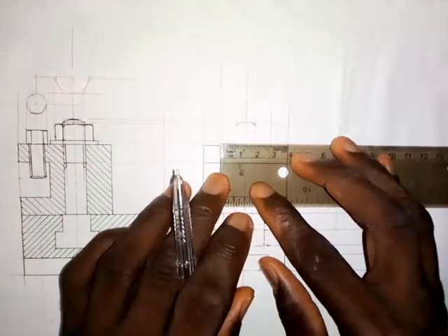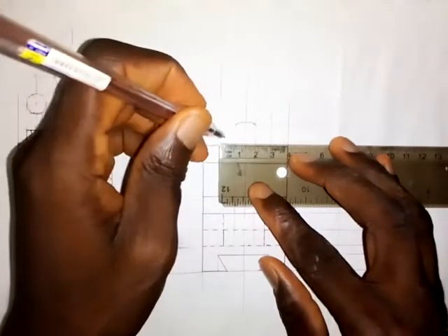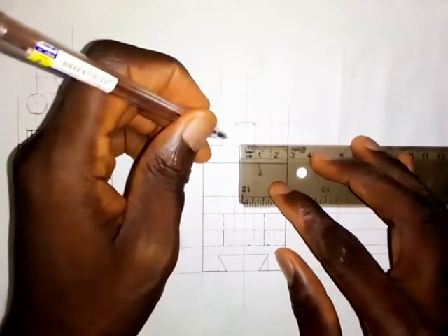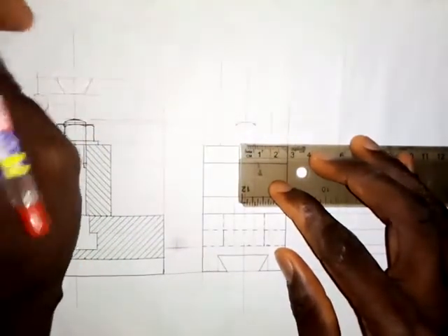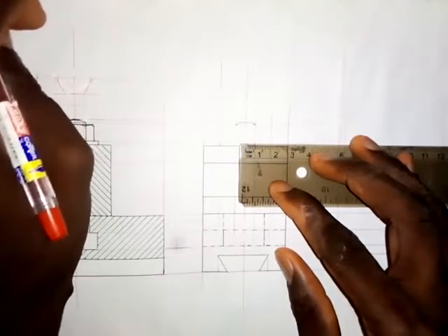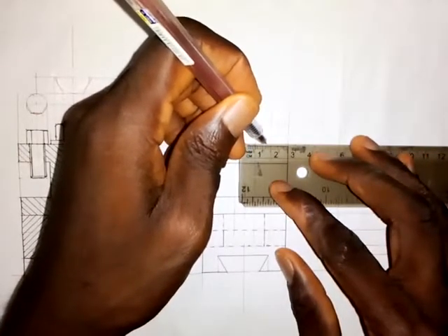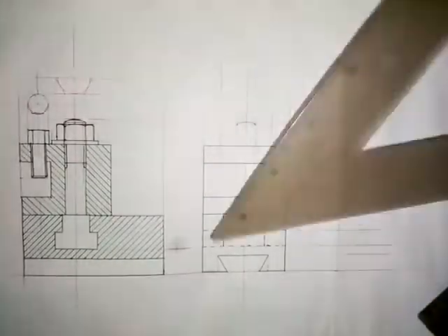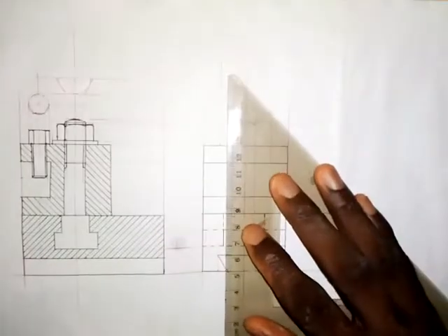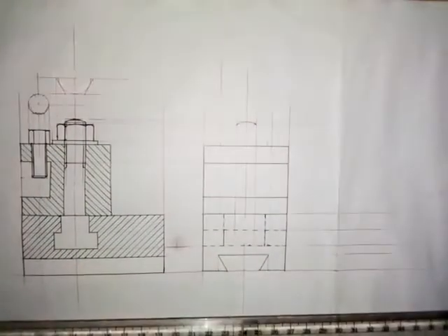I will take a measurement of 13 millimeters to this side, and then 13 millimeters to this side. I'm looking at this 13 millimeters that we are given. I think it will obstruct the set screw. By the time we are putting the set screw, it's going to obstruct it. So I'm not going to put the washer now, but I will just have a partial look of it, because I don't think this is going to work. So just let me leave it like that.